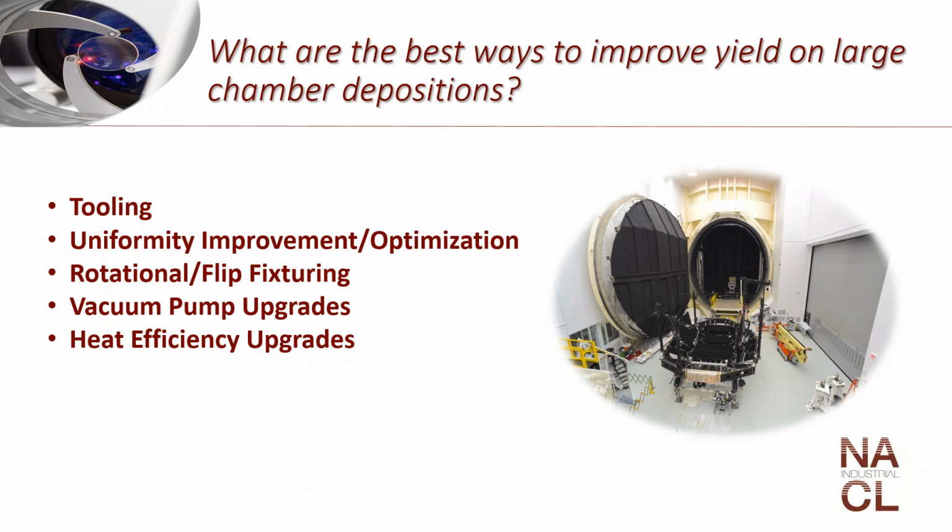And this can be in a few different facets. We've overcome this with just complete chamber specific tooling. Depending on how your vacuum coating chamber is laid out, you have a usable amount of area. And the thing to do, or the engineering challenge, is to maximize that with different coating fixtures. You'd like the most flexibility out of your fixture, but in a high volume application, it's almost best that you make it specifically for the optical footprint of the part you'll be coating.